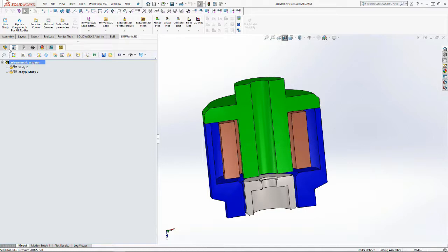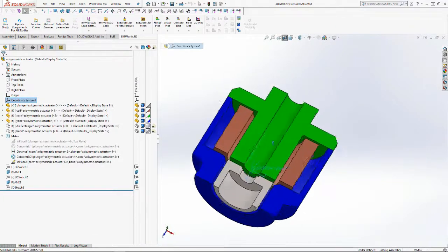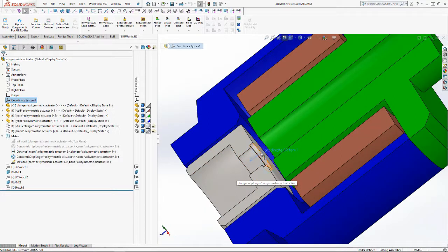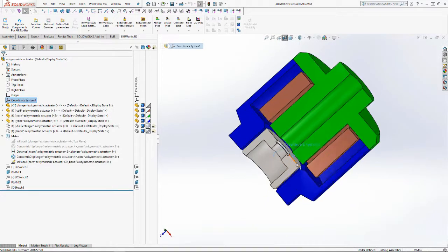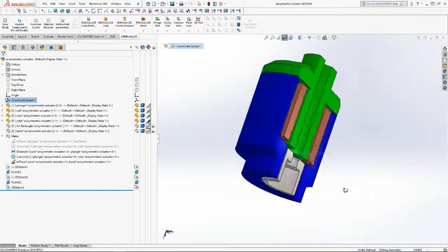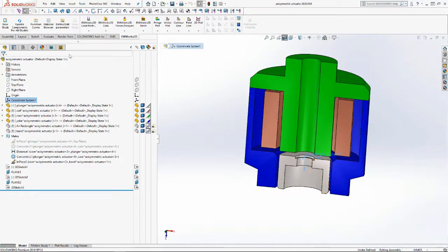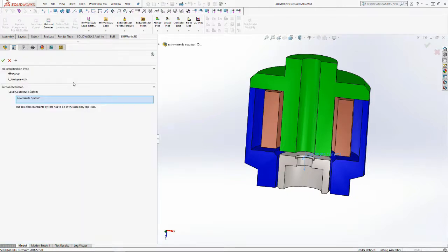You just define a local coordinate system like this. So we have an axisymmetric problem. You should define the z axis along the axis of the model, and put the x axis in the direction that you want to cut your model. So this one, and go here, then use this feature. We mentioned this feature; it's a 2D simplification feature that helps to create a 2D model.